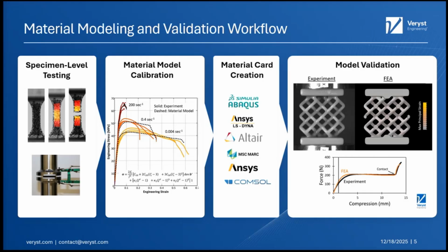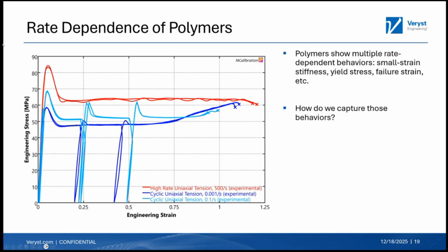The other thing I like to do is take a couple points before you see yield. So if I go to slide 19, yield would be about here. I'd want maybe 1 or 2 points before yield to understand how much plasticity we see before yield, because you will see some plasticity. And then I might do 1 or 2 afterwards. Again, using my application as a guideline for choosing some of those strains.